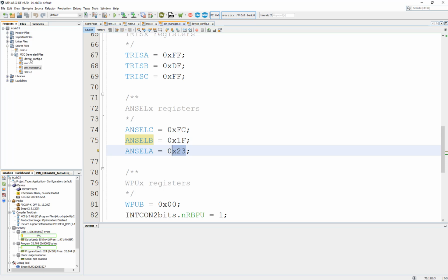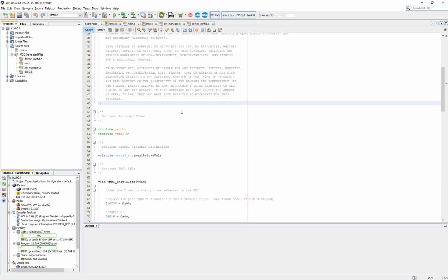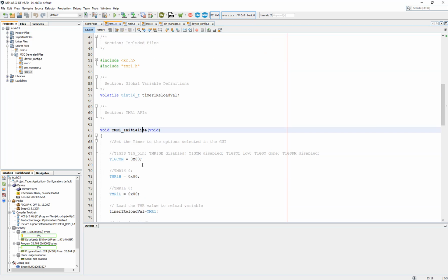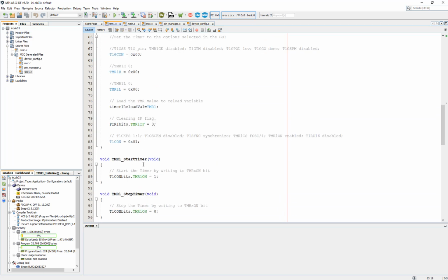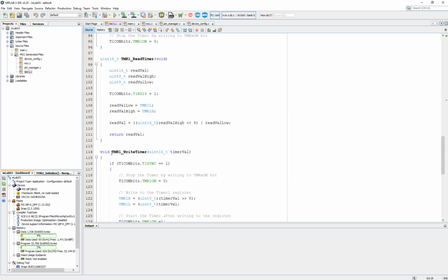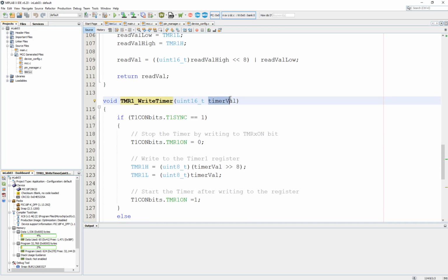Just get into these files, and you can see how they were set up. For the timer, right? I saw timer initialize, and the timer is writing a number here. TMR is timer 1, and you put a number here, and this function will take this argument and shift it, because this timer register, the counts, has two bytes.